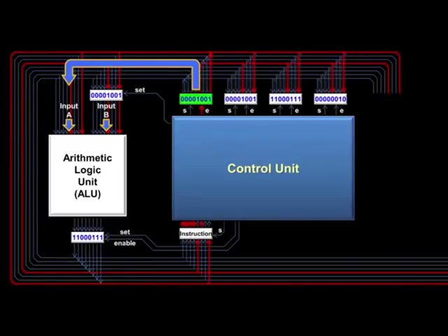By the way, the input wires from the bus won't affect this register since the instruction was already saved in a previous step. This register, like the temporary register, also has no need for an enable wire since it just outputs to the control unit. Based upon this instruction, the control unit then tells the ALU what type of operation. For that, we use the flags that we talked about earlier. Each flag is just a wire that turns on or off depending upon whether or not a certain condition is true. Inside the Scott CPU there are 4 flags, and we'll look at 2 of them now.